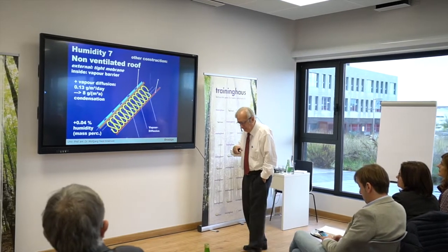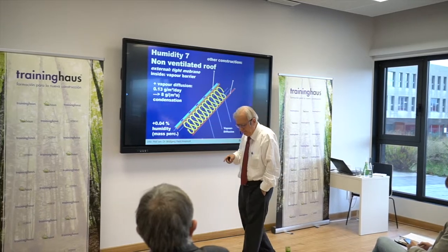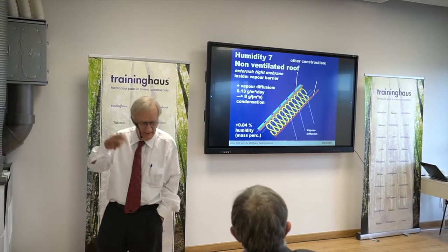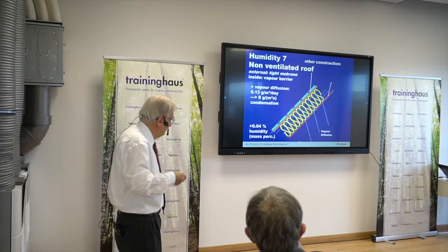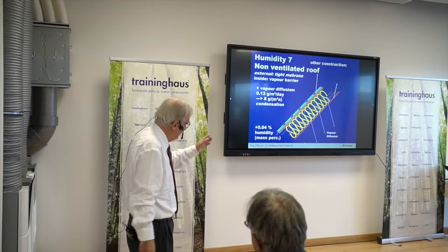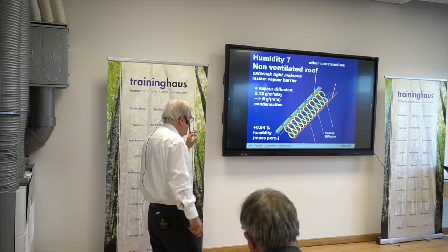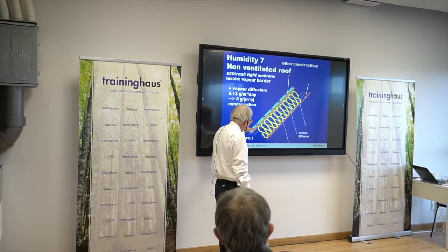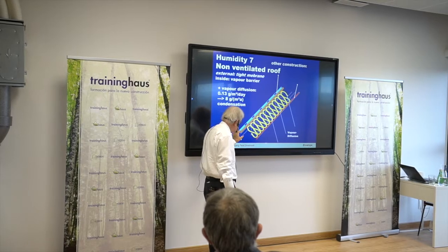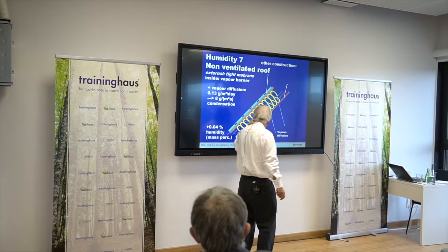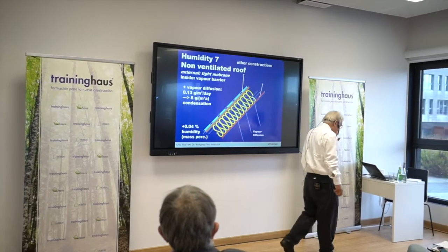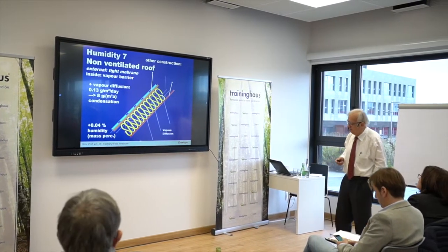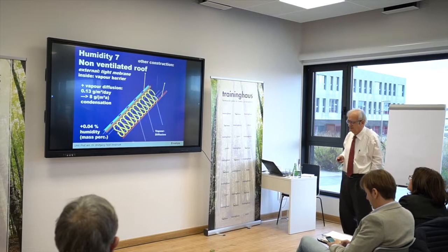In the case of our construction with the tilted roof, it's not that big a deal. You can always make it in a way that there is a ventilated roof. I just mentioned that. I don't want to be understood in a way that it's not important. It's the best idea to do here. So the best idea would be to remove this a little bit, to have a depth of 3 to 5 centimeters of ventilated air, and to have this second layer. It's always what we recommend. But if this is not the case, we are immediately at a completely different situation.